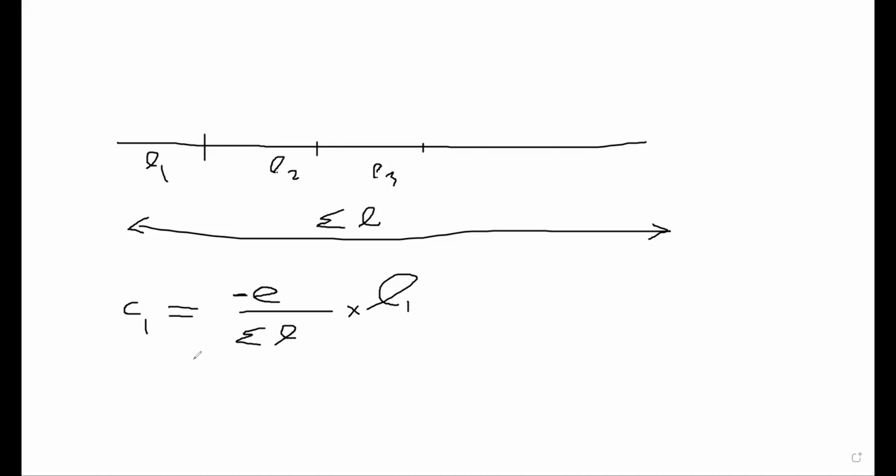If you have the error 1 millimeter, then you can directly calculate the correction. Correction is negative times the error. So for the first case, you want to add 1 millimeter. That 1 millimeter should be shared among 4 members proportional to their lengths, right? So here these shares will come very low as the error is 1 millimeter. But definitely when you do your survey, it will not be 1 millimeter. So you may have some considerable amount of error. Then we can display it, right?